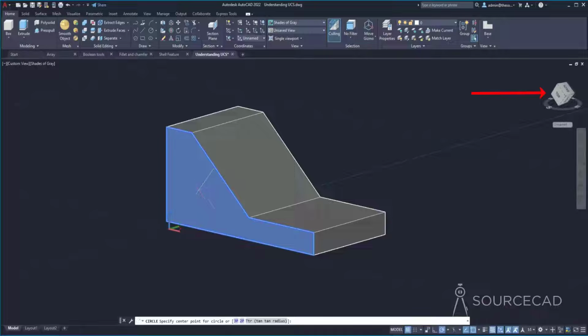Now the left side is top. If I move to this one, well, the right side is top. So here I'll just click, make my drawing, and there we are. And in a similar way, I can make it on any plane. Now, the only condition for this to work is you should have an existing plane or an existing 3D solid. But the previous condition will work even if you don't have anything in your drawing.